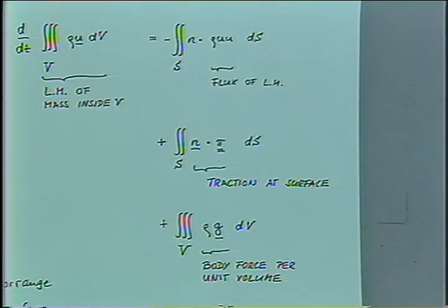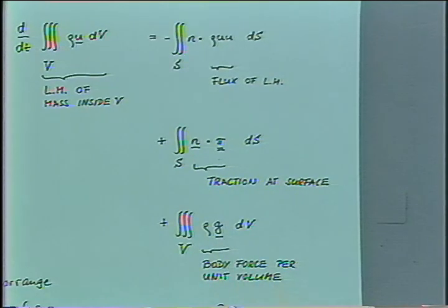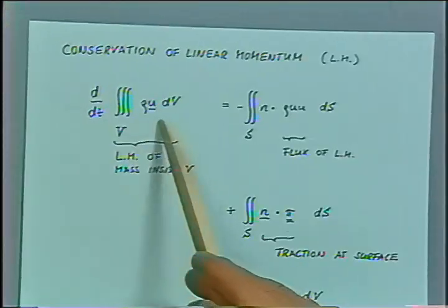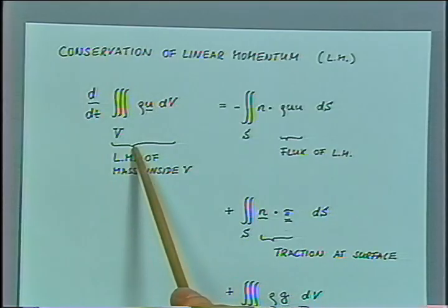You know, we have a large control volume here, so individual material elements might be accelerated or decelerated or affected by some volume forces. This could be gravity, as I put it down here with g, but you could have some magnetic field effects or some other contributions which give rise to a volume force. And those volume forces will change the linear momentum of the system, and they have to be integrated over the entire volume, and they will give a contribution to our balance here.